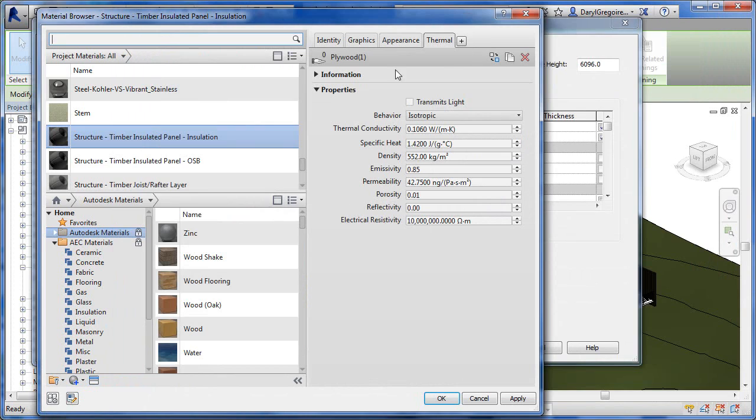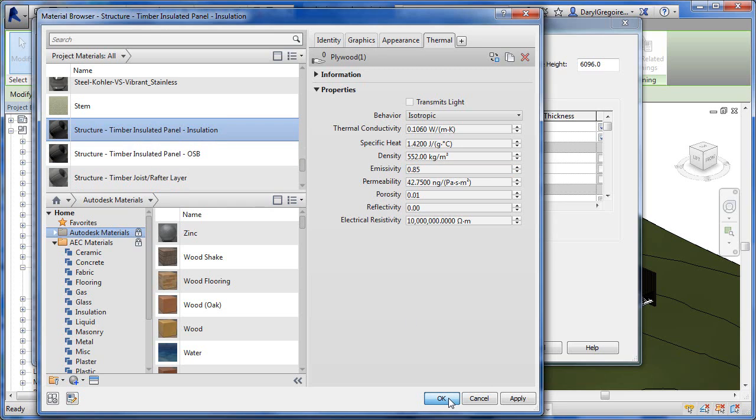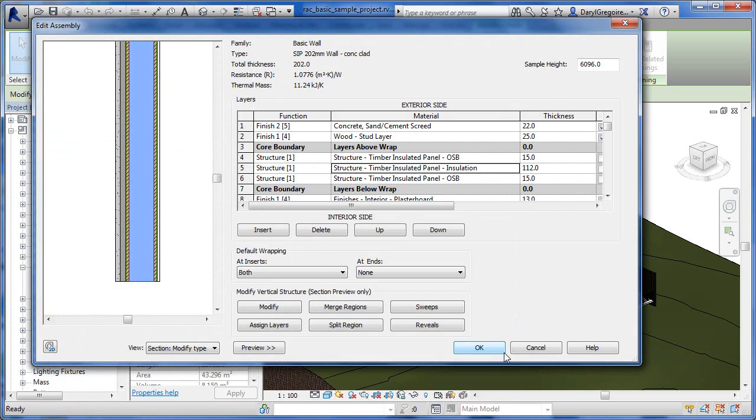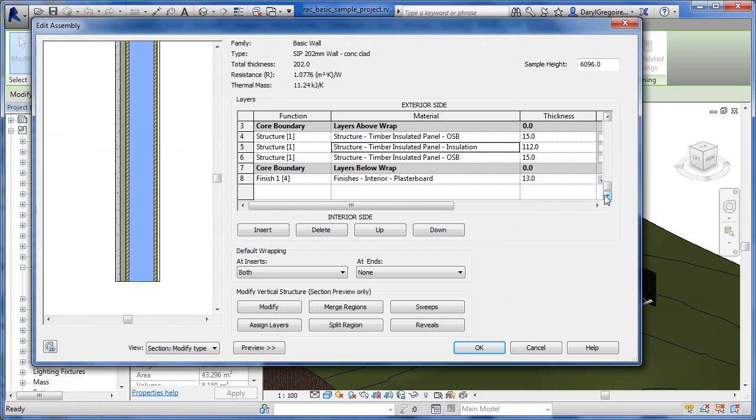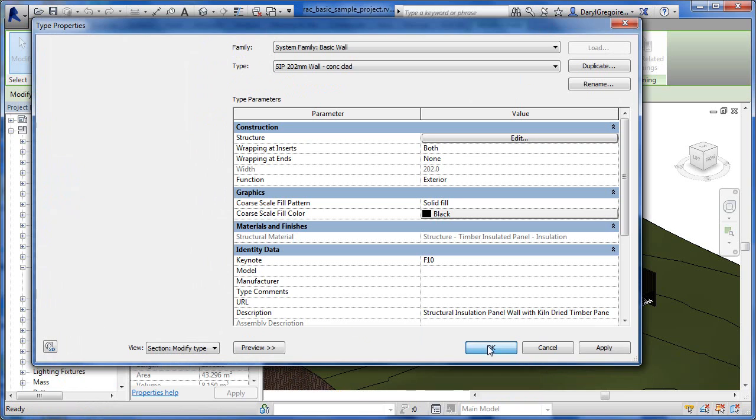Now watch, I close this off and look over here, I now have thermal value, so I can go in and change these numbers. So I've basically added a thermal asset to this material, which for whatever reason didn't have any thermal material properties. Fair enough, hit OK. That's going to change my analysis a little bit. So each one of these components and materials, of course, that make up our wall and floor and roof all get these wonderful little thermal values.